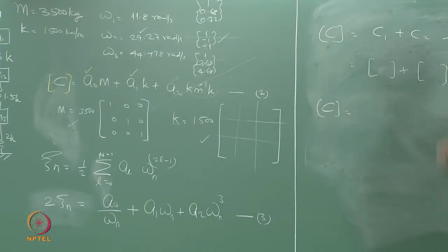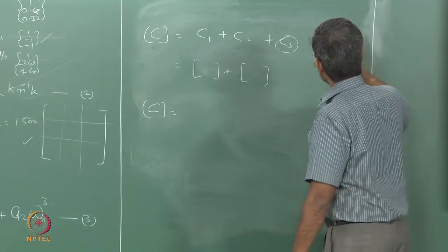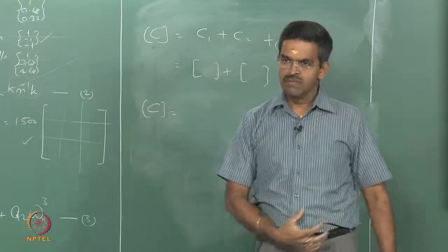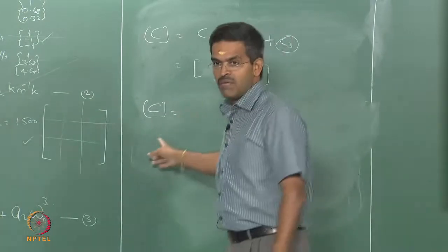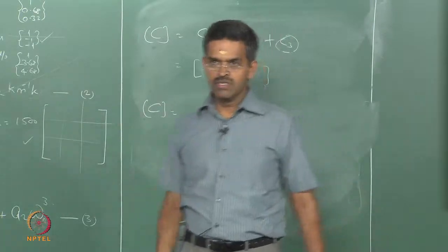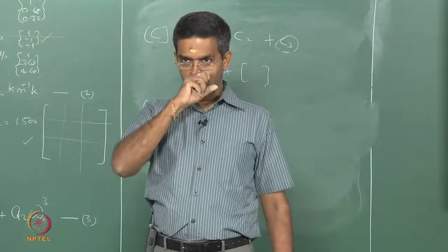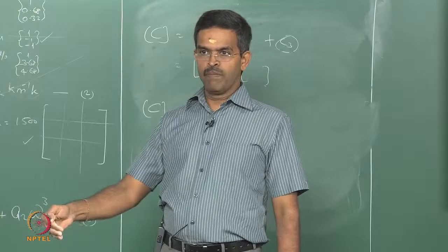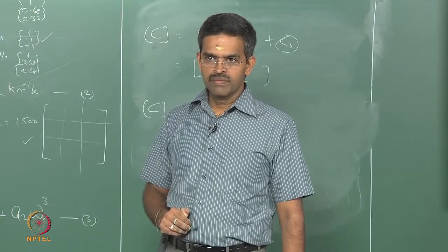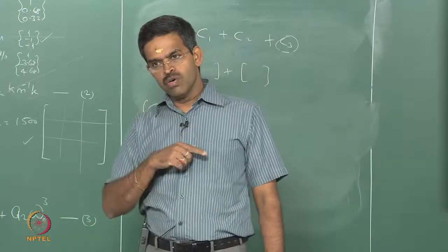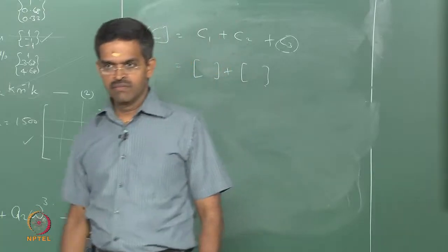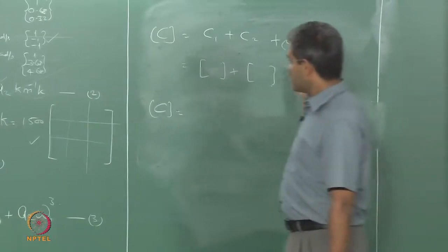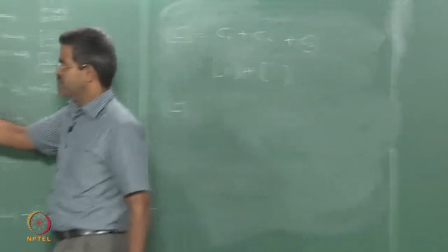Okay. So, if you keep on adding higher modes, you will see that the contribution generally of the higher modes on the damping is decreasing. It is because of this that people said let us truncate the modes and bring down to 3 or 4, but the number is not a magic number. You have got to justify where we should stop the mode counting. Again it will be related to mass participation factor, because everywhere you see truncation of modes related to mass, truncation of C related to mass, you see here.